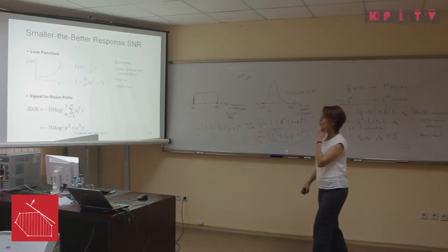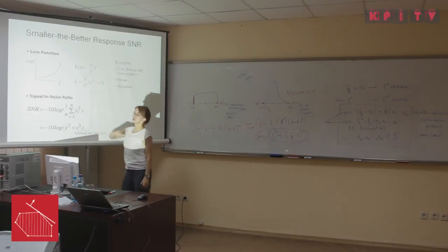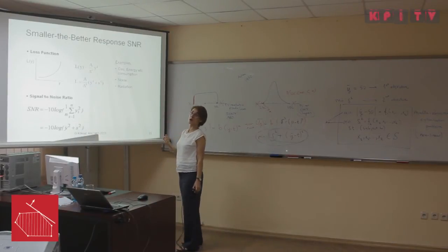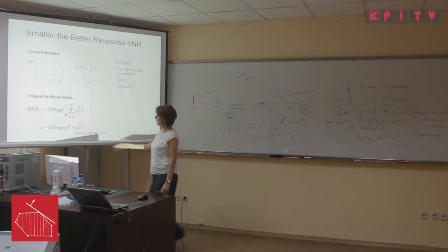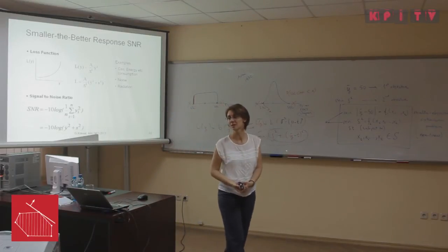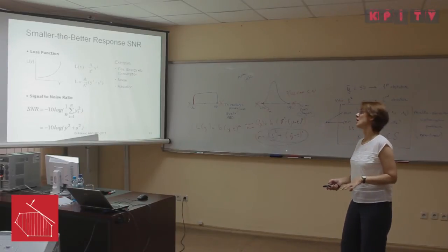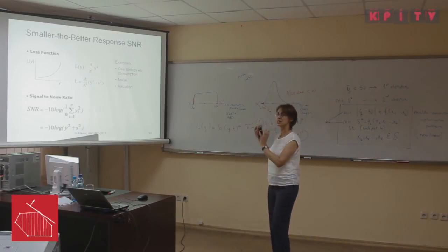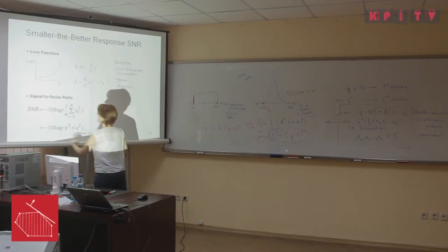And Taguchi proposes to use a very similar figure to optimize, to maximize actually, which is y bar squared plus s squared. You take a logarithm and multiply it by 10, that converts it to a decibel scale, and you put a minus there because Taguchi wanted a small rule for the industry people to memorize. Signal to noise ratios are always maximized. Therefore, he put a minus in the front. If you maximize